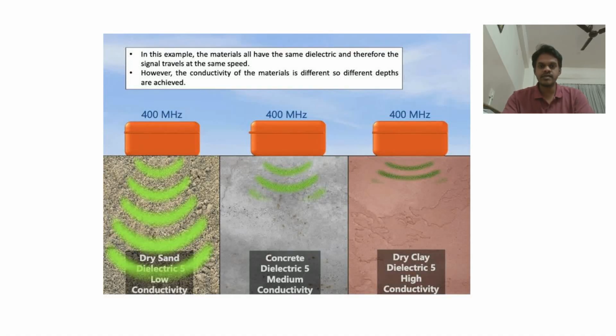So in this video, we will be discussing why clay generally destroys the GPR signals. This is one of the most common reasons why there is poor penetration of the electromagnetic waves into the ground. For example, when you take a clear glass and put some light on it, the light passes through it easily. And when you have an unclean glass, something covered with mud, the light doesn't pass through it. The same way, with GPR, when clay is present, it doesn't let the radiation pass through it.